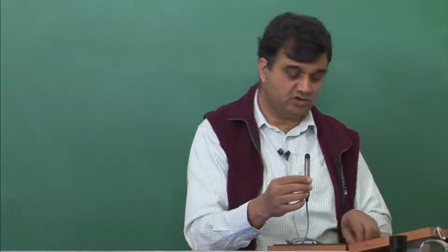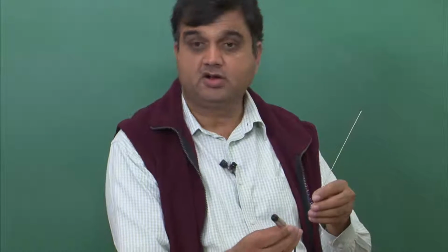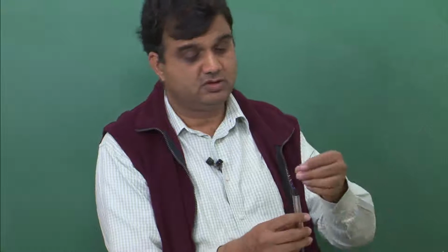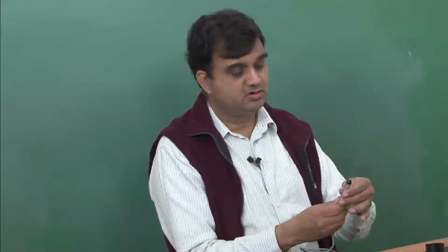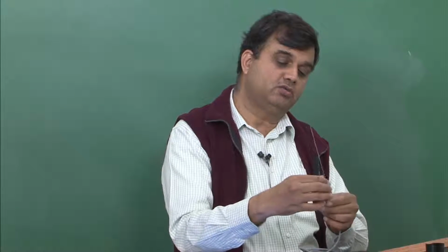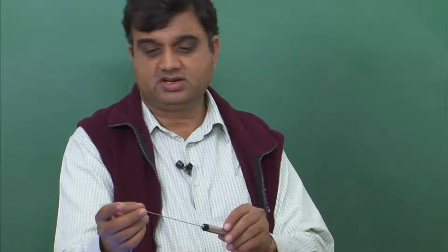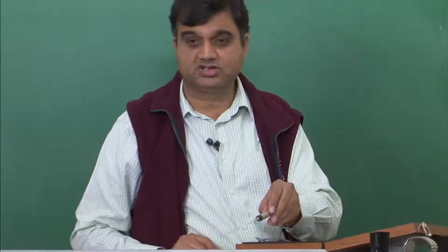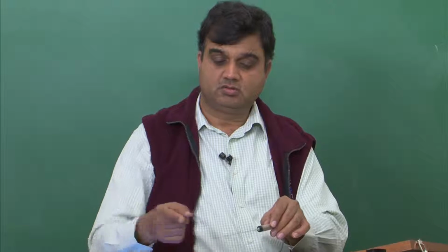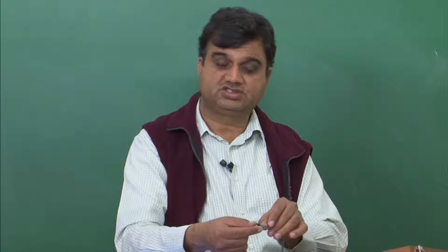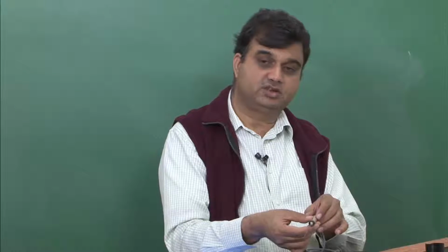So what you have is some sort of a tube, and this tube cannot take a lot of high temperature like other regular microphones. But if you have noise in a high temperature zone, what you do is you attach this hollow, thin, slender stainless steel pipe to it, and you insert this pipe into the area where you want to sense the sound pressure level at high temperature, and so all of a sudden all the hot temperature will not reach this side, and if you are careful you can protect this microphone from high temperatures, and you can still manage to take